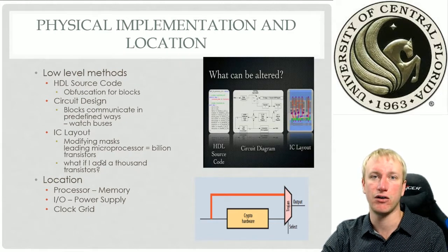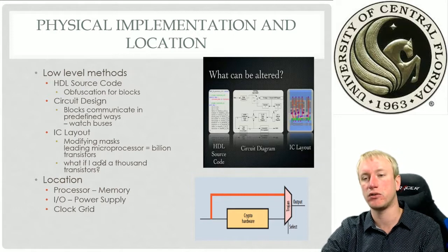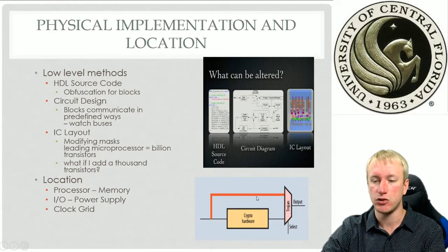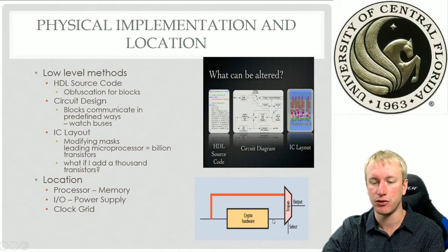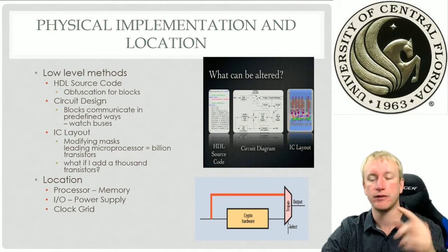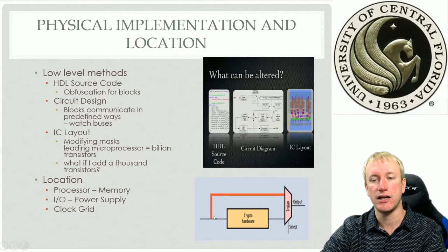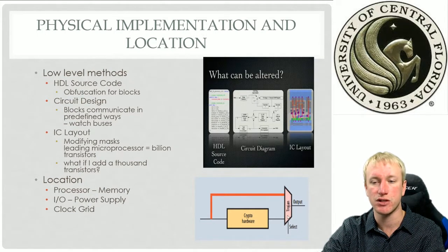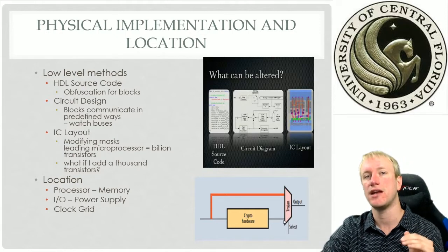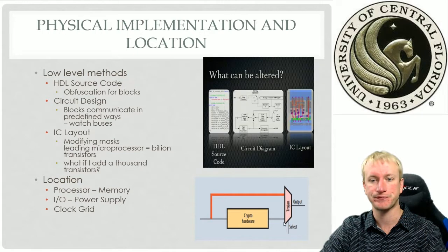So what is a hardware Trojan? What does it look like? The basic form of it can be shown right here in the bottom right. You have your message being sent through and it's encrypted, or was. Now I as an attacker put a mux or a switch with my little flicker per se, and then the output. So say you're sending an encrypted message to a friend, I can then flip this mux or the switch saying, hey, just send me the clear text. Now I know exactly what you said without it being encrypted because of this one little switch in there.